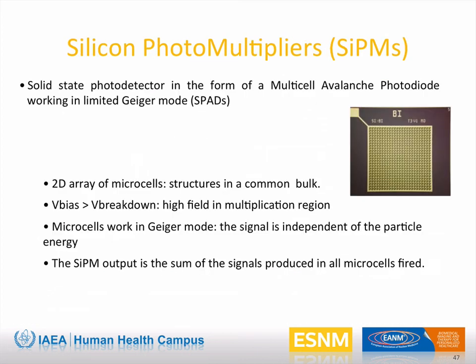Another example is the silicon photomultiplier. Now, let me briefly explain how a SiPM works. When the bias voltage on an APD is greater than the junction breakdown voltage, the charge multiplication is a diverging, self-sustaining process, called Geiger regime. This process results in a very high gain that can be quenched using a quenching resistor. A device based on this working mechanism is called single photon avalanche diode, or SPAD.